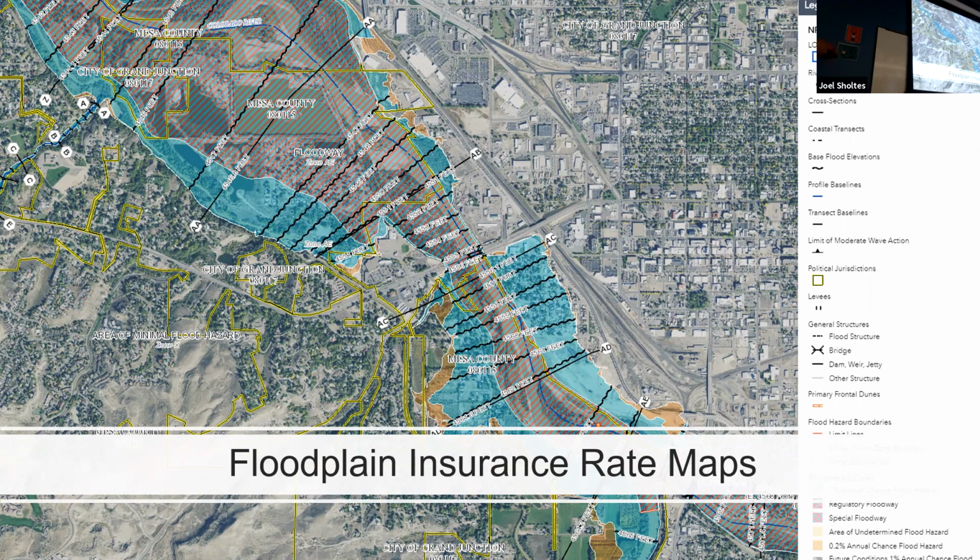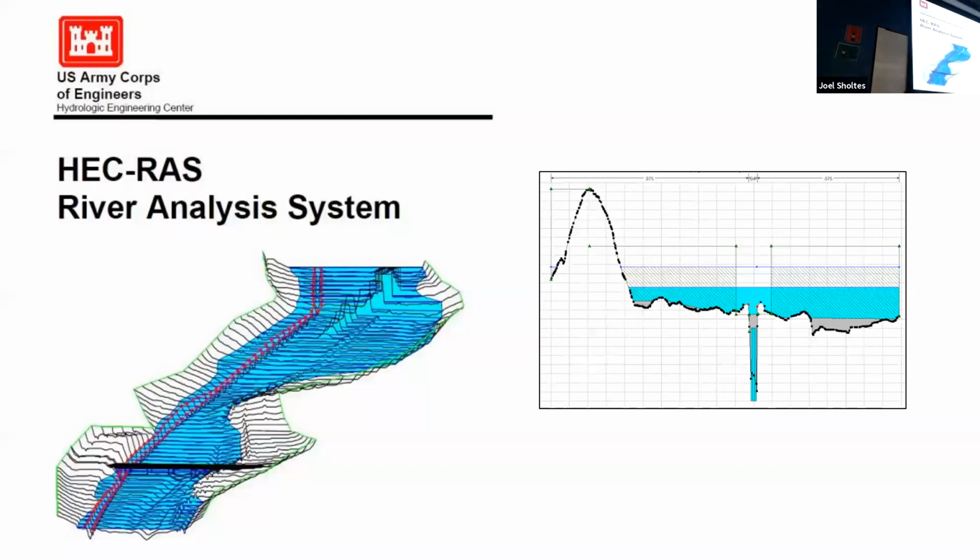And in some cases, you can see it's a little more dramatic, but across the Colorado River in the Grand Valley, there's a pretty high bluff on a lot of these areas. And so there's going to be very little difference in the floodplain, the 100-year and the 500-year. That's going to change. If you're out in a more flat area, you're going to see a really big difference between those two floods. But where you have kind of high walls, there's not a big difference.